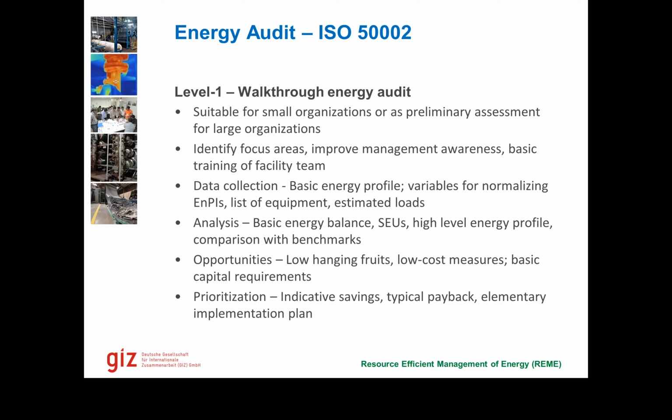Then conducting a very basic energy balance at the energy input level, that is, how much percent of energy you're getting from each of the energy types, and just qualitatively assessing what are the biggest energy users. At this time, we might not have enough data to actually quantify the energy users, but at least we might have a very high level of energy profile rather than having a very detailed one. And as everybody has been saying earlier, low hanging fruits, low cost measures, basic capital requirements, these are the opportunities that we identify here, and where we can start building trust in the company.